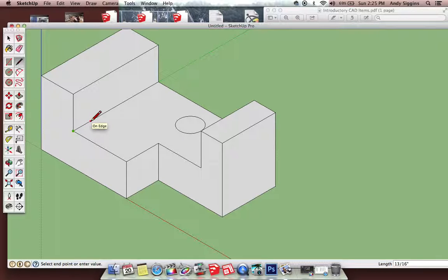So I'm going to walk in 1 inch from the front edge, and that puts me into this corner 1 inch. And then I'm also going to walk out into the object 1 inch. And I've now got the center of this circle identified, from which I can click and create my circle. Now you could type in 1/2 inch, or because you've used a 1 inch line to find the center, I can come back out to the midpoint, and the blue dot is 1/2 inch away from the center of that circle. And I can now click and again create my circle.